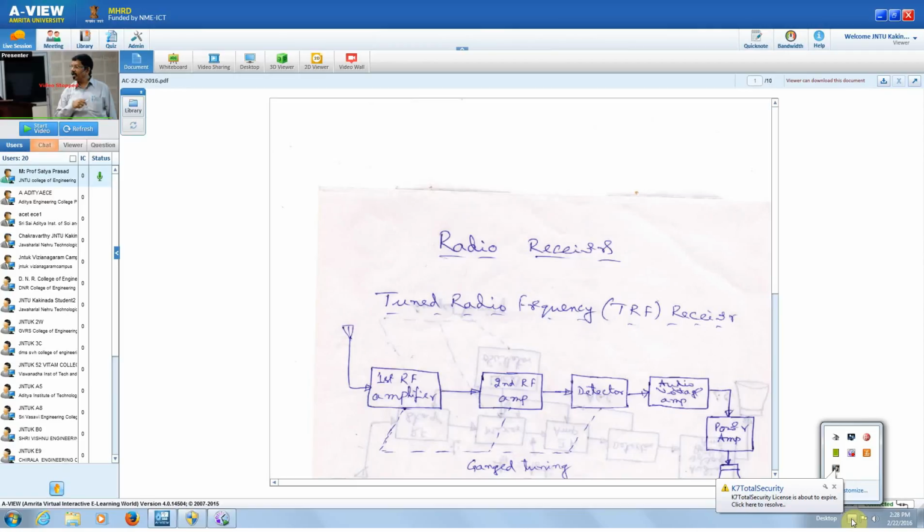If they are in phase and having a sufficient amplitude, then without any input from the antenna, the output of the second stage amplifier itself is sufficient to give the required output. Therefore, oscillation starts, because all the amplification we are providing in these stages of your tuned radio frequency receiver is very large.